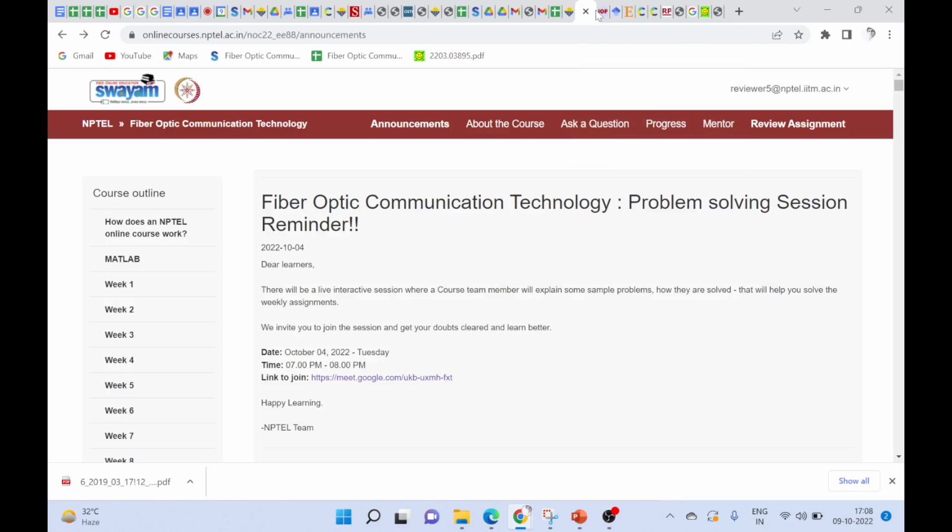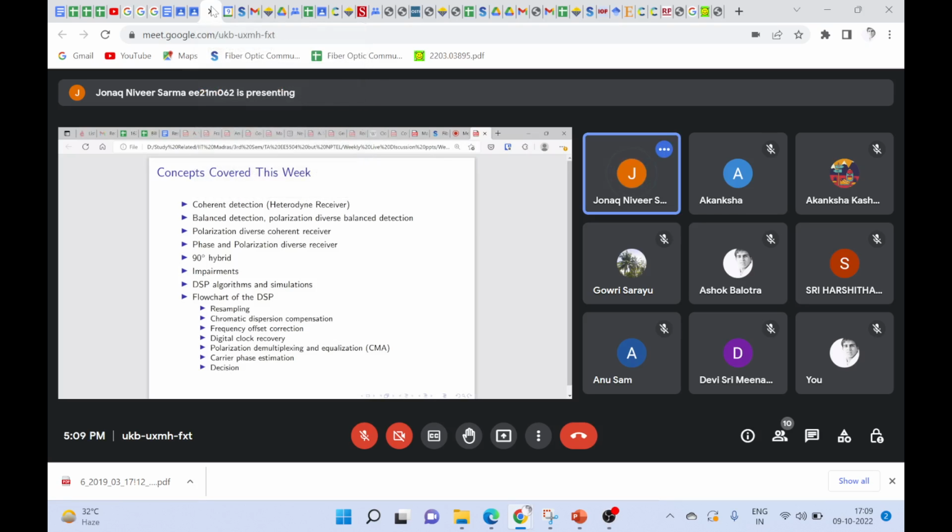Anyway, we started this week with a quick recap of coherent detection, what was covered when we were discussing photodetector noise and all these concepts. Then we went on to discuss balance detection using 2x2 couplers and how to adapt that same structure by using polarization beam splitters. I think polarization beam splitters were not discussed during the components week last week, but I hope everyone got the concept.